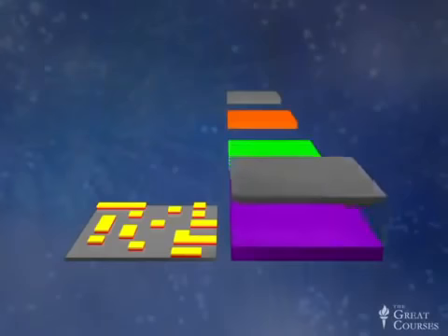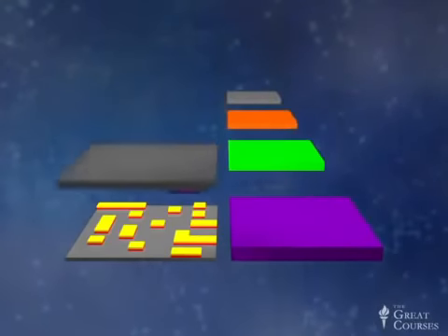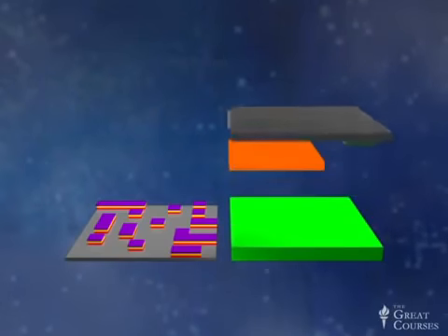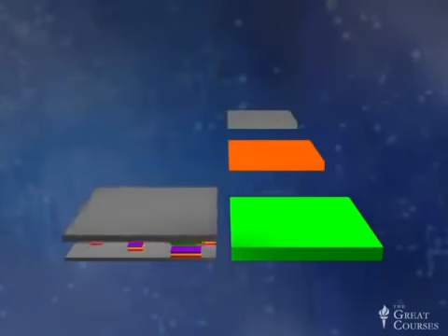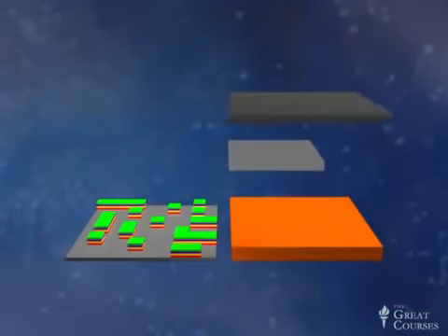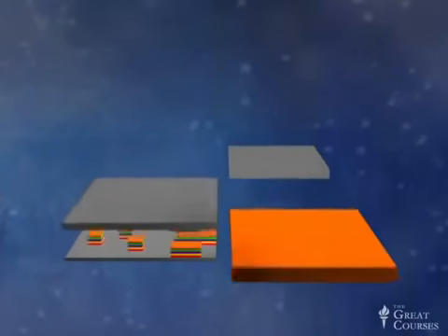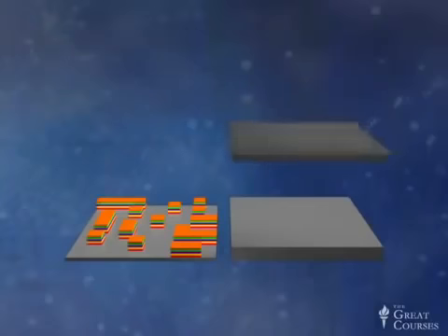He's able to use repeated application of this additive process that uses these soft stamps and these donor substrates that donate their materials that we've coated onto them and integrate them onto a stack to make a three-dimensionally structured, heterogeneously integrated material. He's able to combine in this way both rigid and flexible materials and devices. That combination is very powerful.